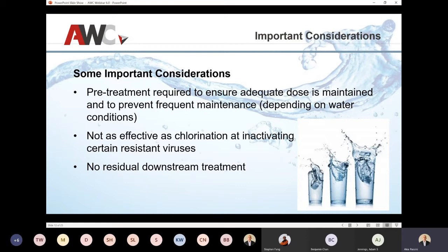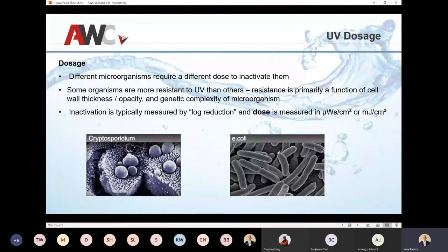So for those of you that might not be directly related to the water industry, residual basically means the amount of free chlorine that's in the water that will continue disinfecting. UV is a barrier, and it should only be considered a barrier, which basically means you're putting up a wall. You're disinfecting any water that's going into your chamber. Anything after that is not going to be completely treated. So if you're going into a city where you have 200 miles of pipes, that doesn't mean that all 200 miles of pipes are going to be disinfected. It's just all the way coming out of the treatment plant.